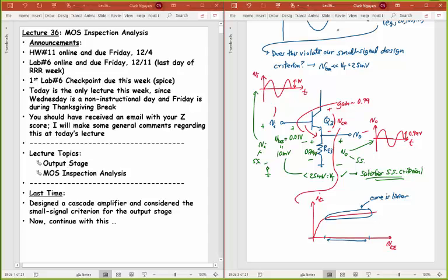If I had a signal in the time domain that was doing this, we're not violating any of our small signal parts here, because what small signal is trying to do is linearize things, and this curve is linear over that range. It's no longer a small signal, but it's still linear. So all of our analysis still works there. Where it goes nonlinear is at this point.